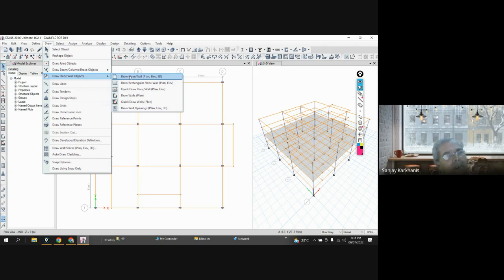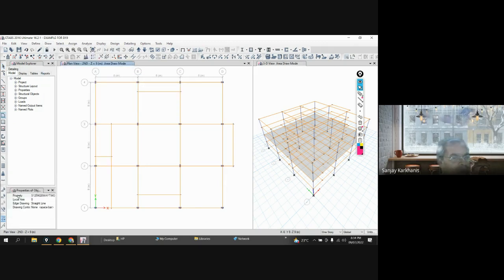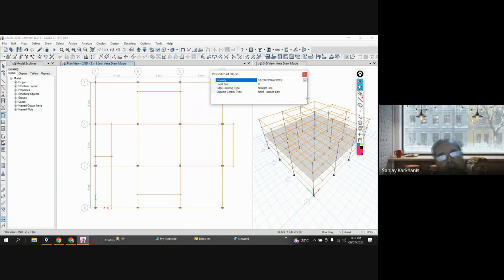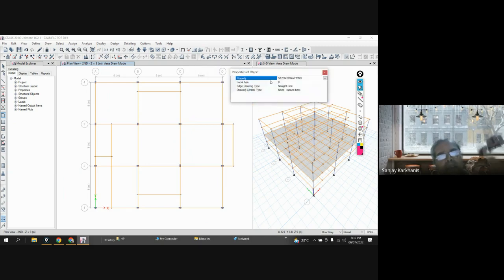So let's say click on that draw, then go to property, so bring it somewhere here and enlarge it so that you will see what property. Okay, so 125 way 2 is the property that has been selected, and right now you are happy with that, so you will select the points. So 1, 2, either clockwise or anti-clockwise. Periphery.